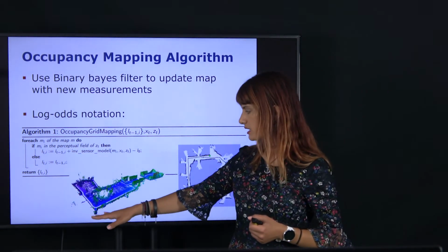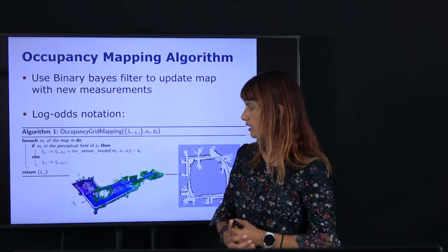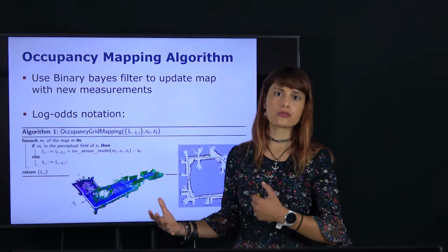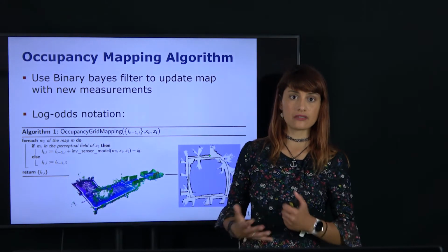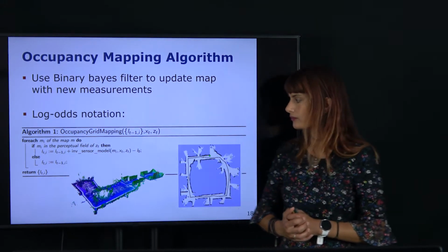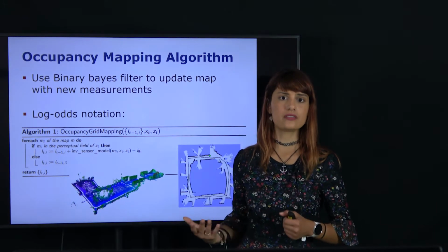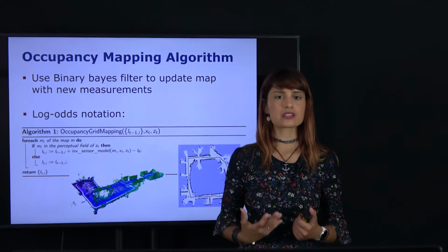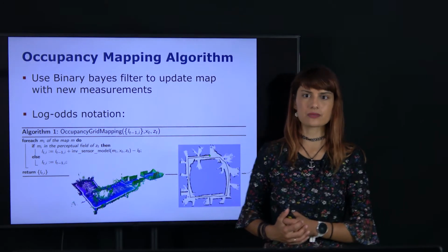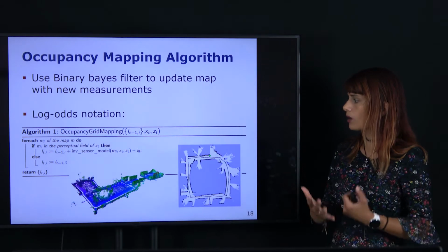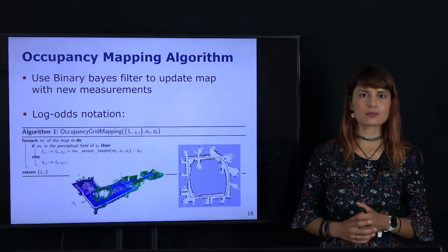And on the left, we see a color-coded by height 3D version of an occupancy grid, the so-called OctoMap, which performs the map updates and stores the map information in an efficient way using octrees. This is exactly the type of map representation that was used in the UAV examples, since they were exploring 3D environments, also using their ability to change height to take measurements. And now we actually have all the ingredients that we need to come up with a basic robot exploration strategy.